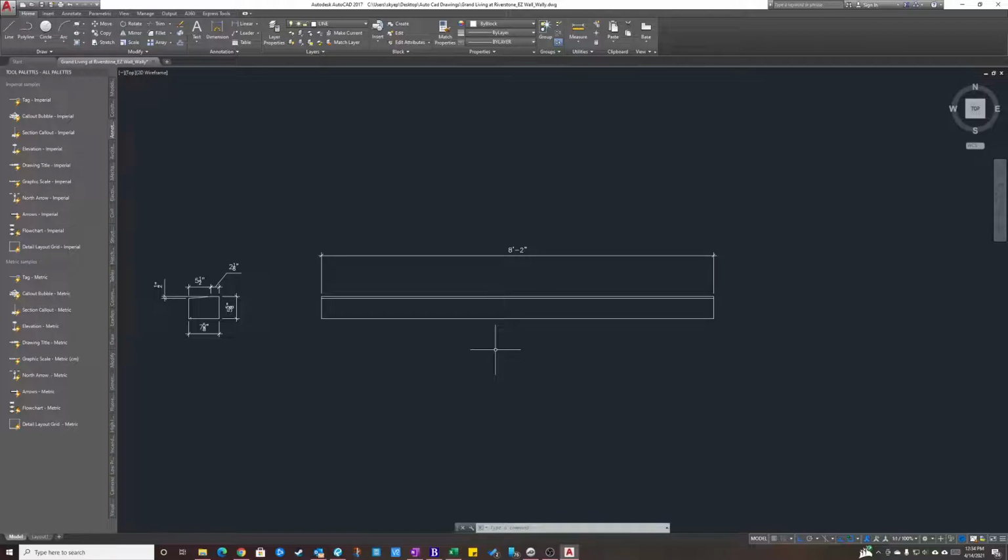So to split this into 3 even pieces, it's a little more complicated than what you might think. The reason why is because you have to reduce the amount of space that's in between the joints. The way to do that is you take a measurement. Your overall measurement is 8'2". Now the joint spacing that we're going to give on these window sills is 3/8 of an inch.